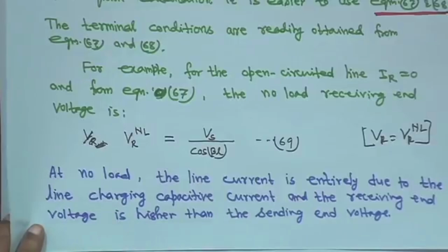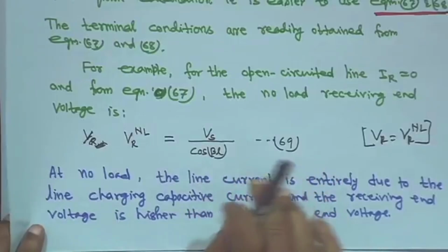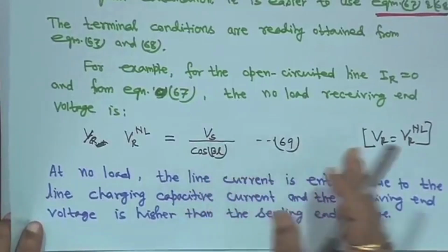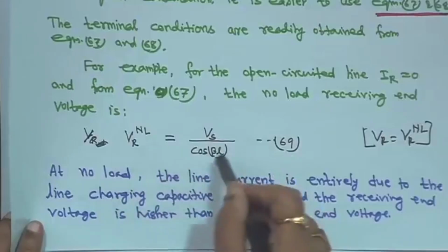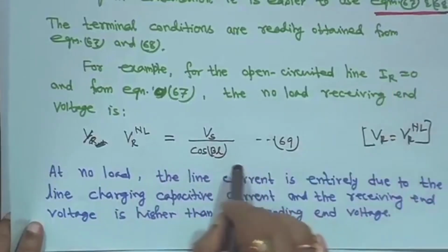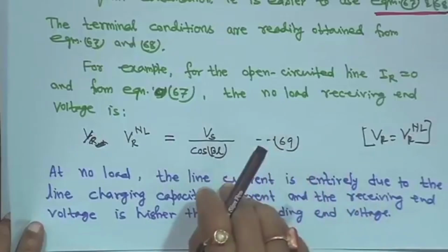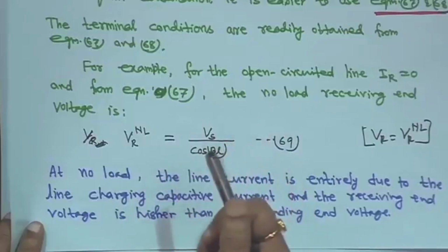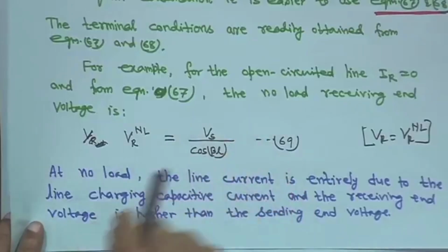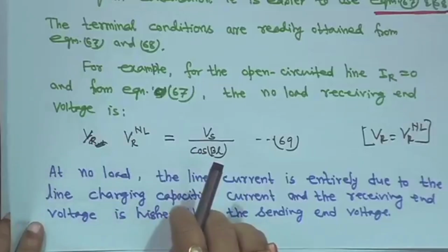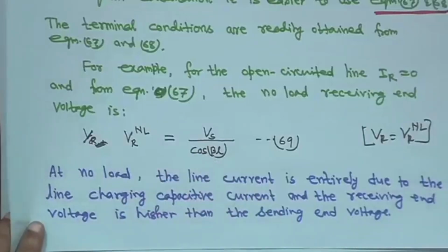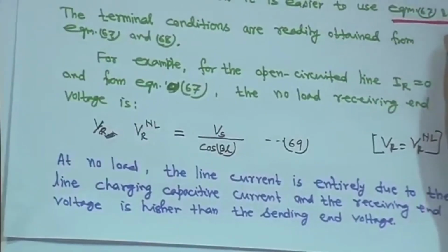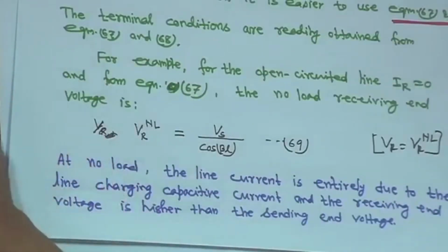I repeat this. Suppose a high tension transmission line was carrying power, but after that the load is disconnected. So, now in this condition IR is 0, right, but a man standing on the ground with bare feet, say, and taking a conducting rod and touching that conductor, that is the line, what will happen to that person? This is a question to you. Later, when you are listening to this, you can send your answer to me, but here I am not giving that answer.